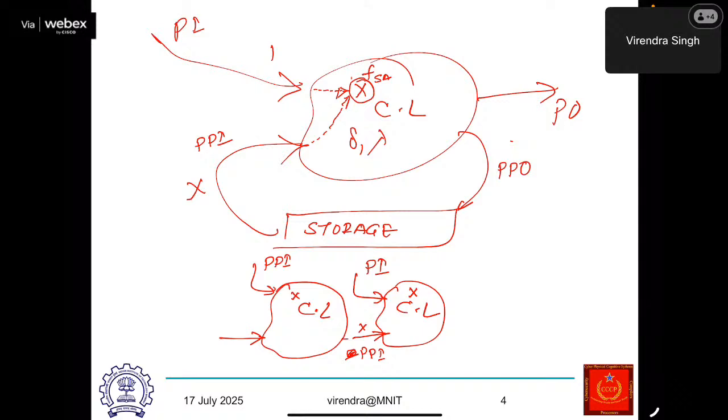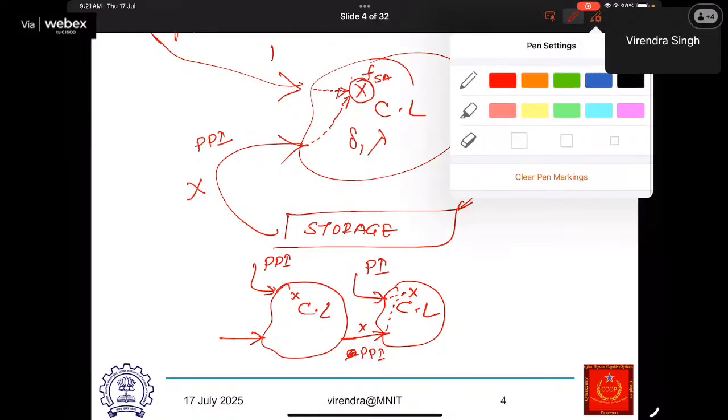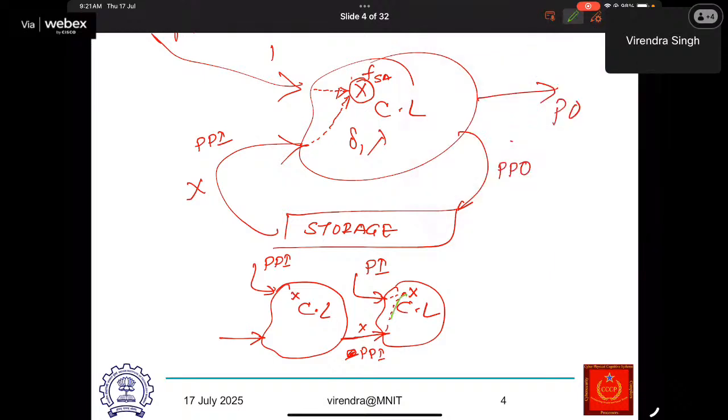Keep in mind that when I'm saying that we are making a copy, it doesn't mean that we are making a copy on the chip. On chip there is only one copy. However, from the test generation point of view, in software we are making the additional copy, and you keep on doing this. Say that this is coming from here, but now if I need this only from this primary input, and you need x from here, in that case you can stop.